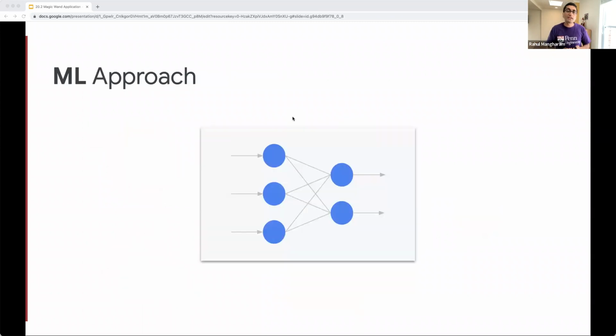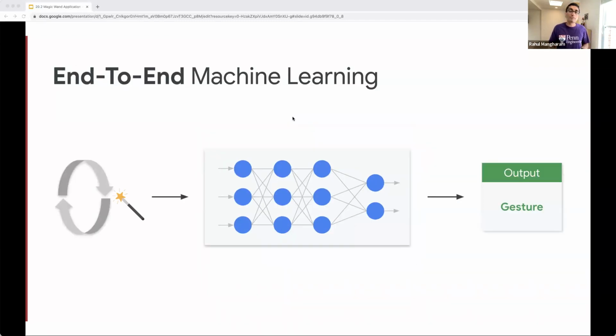encoded in the image. And so one approach is to just take the raw sensor data that we have coming in from the IMU, and feed that straight into the neural network and ask it to predict the gesture. What if we just do that kind of end-to-end approach, right? That would be this end-to-end learning method. Now this would require a lot of data and a fairly large model in order to get good accuracy, especially on complicated gestures, right? So this is not really a preferred method if you want to do things in a tiny ML system.